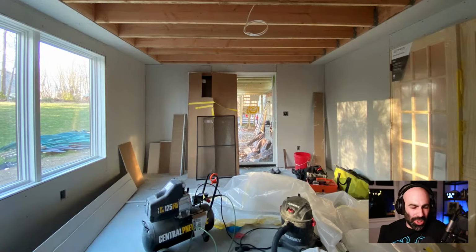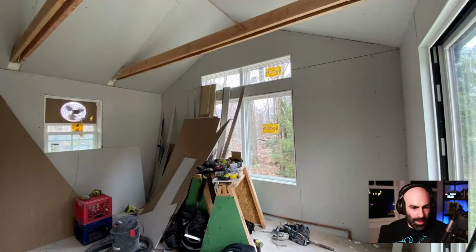Ideally, you'd also want a little bit of bridging, something that breaks up the thermal bridging between the sheathing and the 2x. I didn't, and I don't think I'm going to have any issues, especially because the R value of the full wall is just astronomically large, and we don't really see too much of that. Ideally, you'd want a little bit of a thermal break there, but nothing yet. But you just have to make a decision. If you're going to do that, then you're making a closed, hermetically sealed box. Basically, you want to make sure that you're closing it off, and then you shouldn't run into too many air vapor problems. So yeah, let's keep rolling through this.